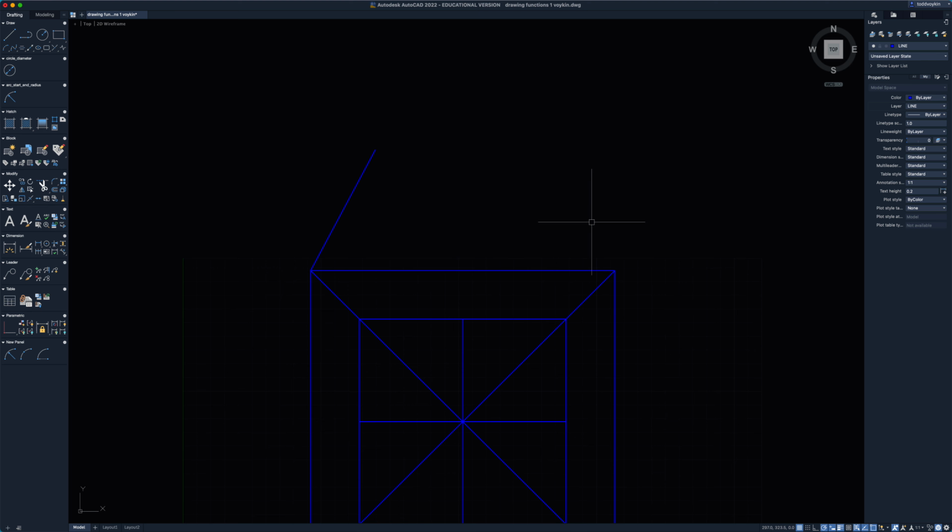Okay, and again, I'm going to right click to go out of there, right click to go back in, and now it says to make a line that goes up but to the left at 62 degrees. Now if we look at that number that's indicating our angle, right now it's saying 119. So basically it started here at 0, and then it went up to 90, and then it keeps increasing here.